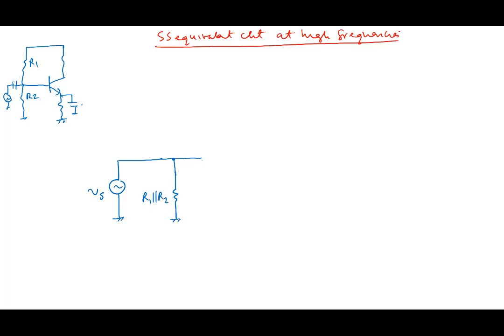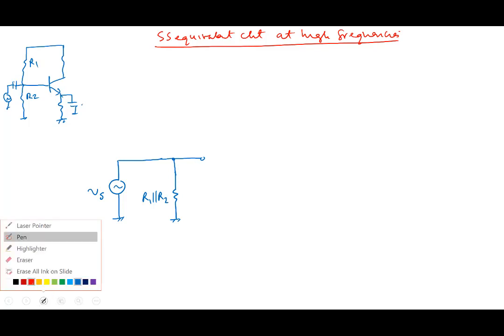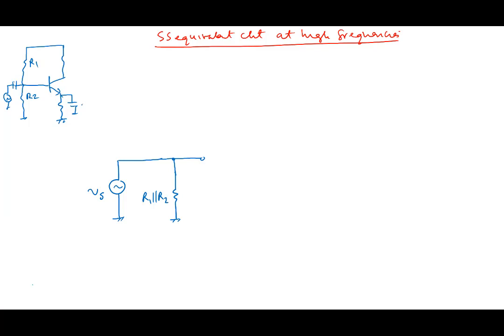Now comes the transistor. Now the transistor model, high frequency. So in the transistor model, we said when you go to high frequency, include this resistor, the transistor resistor, which was RBB, extra resistor here. Put here R pi. Include a capacitance C pi.